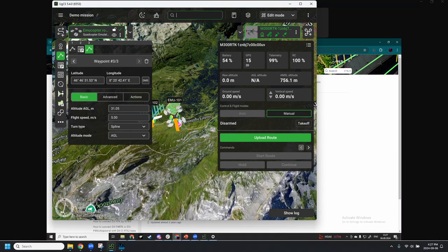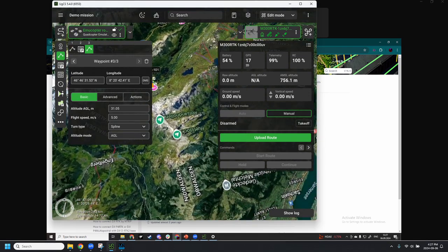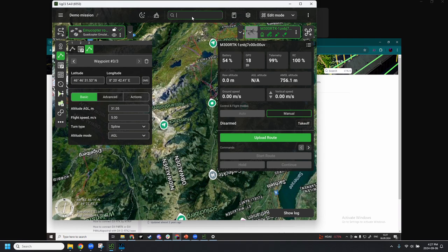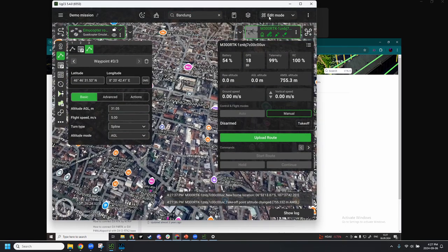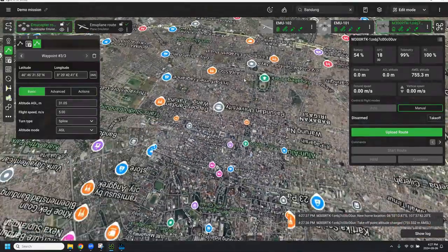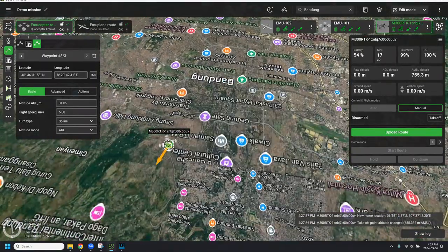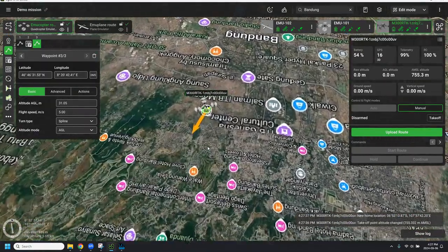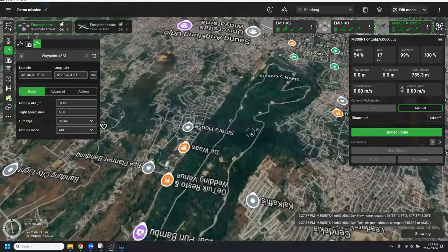Yep, I already did that. And if you want to simulate the flights, emulators are nice and all, but they're based on ArduPilot, and depending on the firmware and specific models, all drones can be a little bit different. So in this case, you can set up a simulation with UGCS for DJI and try flying the routes that way before flying for real.